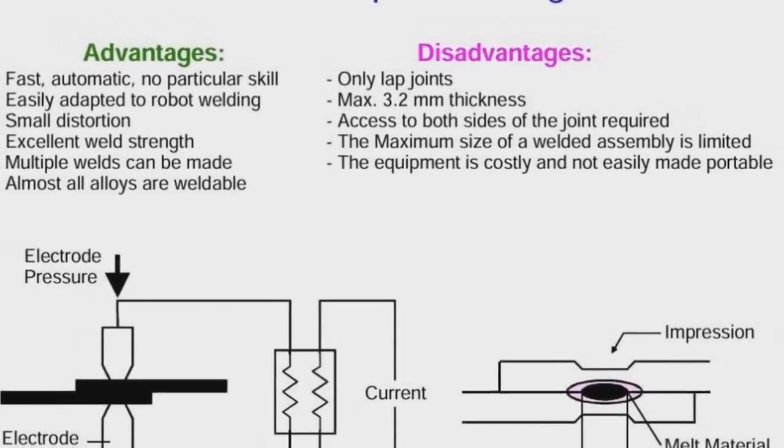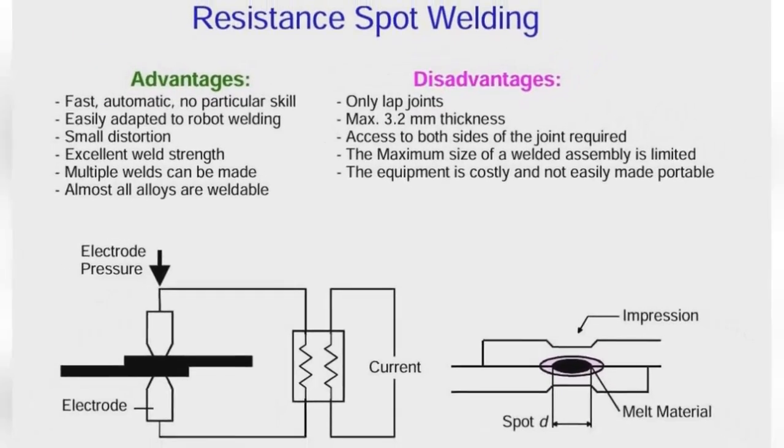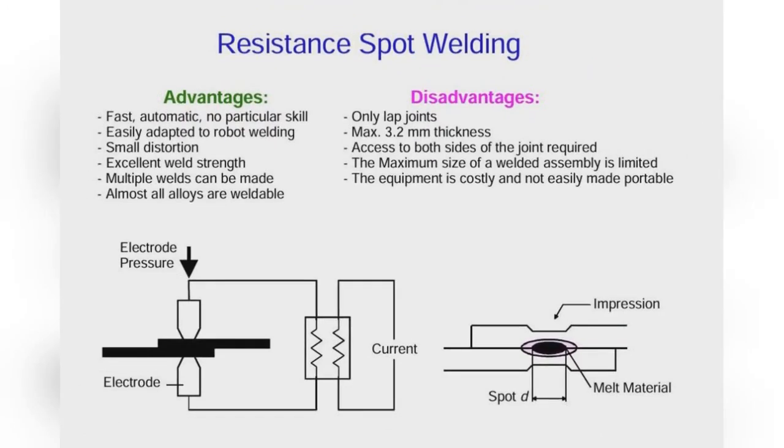Resistance spot welding produces a local weld spot by clamping 2 or sometimes more thicknesses of metal between 2 electrodes for a brief interval, with the metal under pressure. The heat required for coalescence is generated by the bulk electrical resistance of the metal and also by the interface resistance between metal thicknesses. It is a fusion welding process because melting must occur at the interface between the joint members to cause coalescence, form a cast nugget, and join the members together.